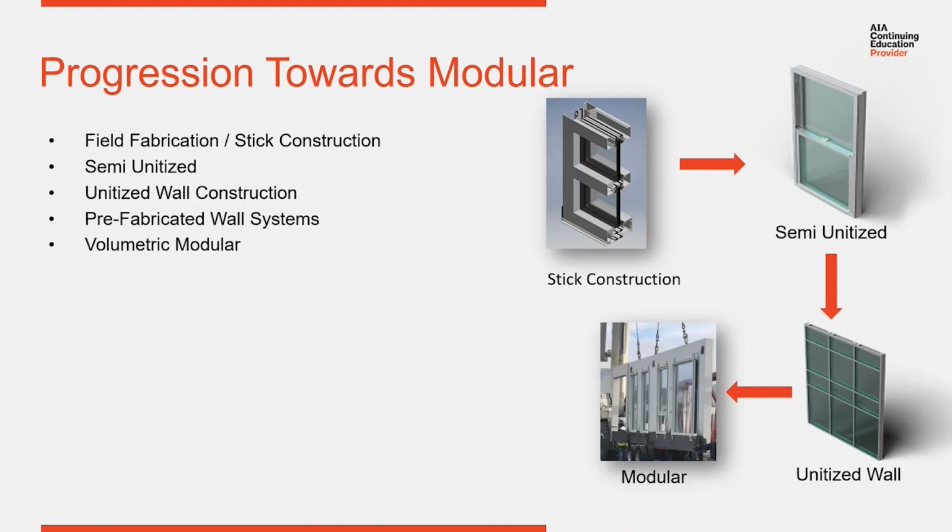So general contractors started looking at, okay, this concept of unitized construction has been great in glass and glazing. Can we combine other trades together? So the concept of modular construction started over the past few years, has been growing. We're seeing more of an interest in it, because modular construction is now taking the concept that was started with unitized curtain wall systems and combining other trades together, because you don't always want glass and glazing on a building. You might want to have precast, brick, other materials. So modular construction is bringing these other components of the building envelope together and building a module containing multiple components of the building envelope in one.